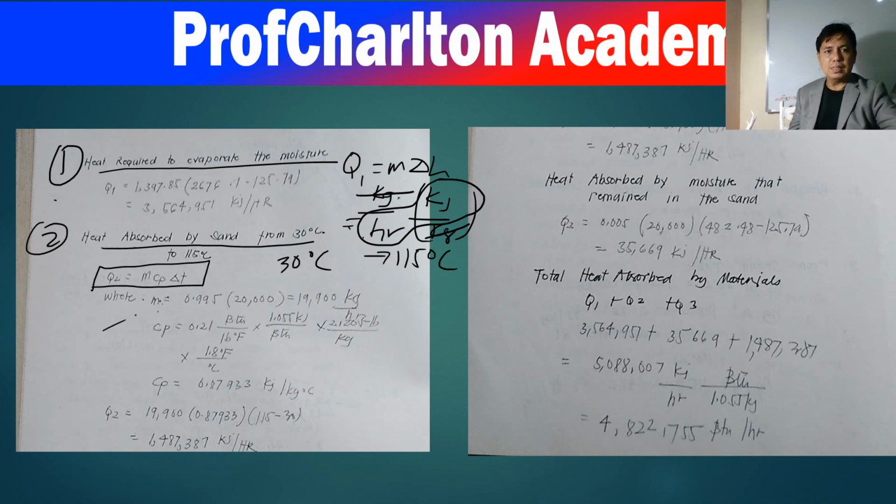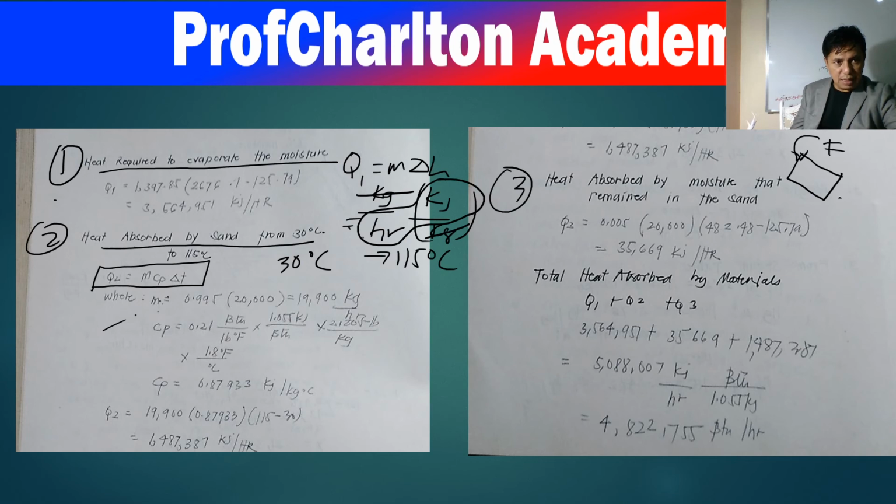So that's the second. The third is this one: the heat absorbed by the moisture that remained in the sand. Meaning there's sand after the dryer. Here is the rotary dryer, here is the feed, and here is the product.